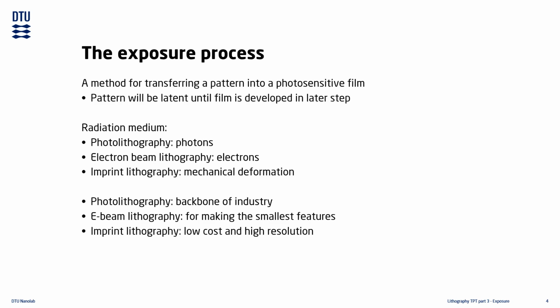When talking about exposure as a lithography process step, imprint lithography is not normally part of that talk, since it technically does not expose the resist to radiation. Imprint lithography is mentioned here because it is a method of pattern transfer, but for the rest of this lecture, only radiative exposure methods will be used as examples.